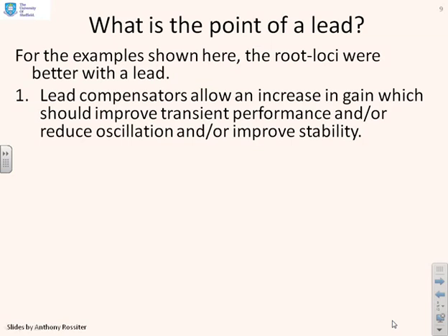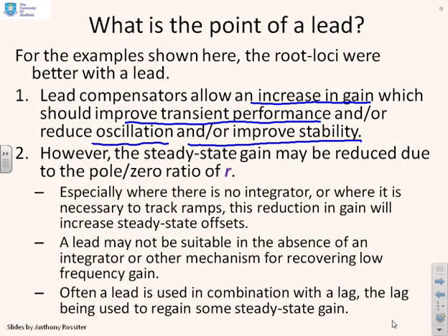So what's the point of the lead? How can we use it? Well, hopefully it's almost self-evident. Lead compensators allow us to increase gain, which means we can get a better transient performance, a faster transient performance. Alternatively, they can allow us to reduce oscillation by moving these loci further left, and or to improve stability.